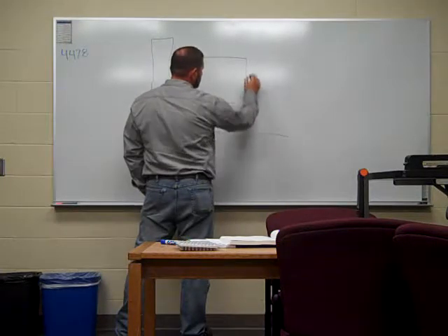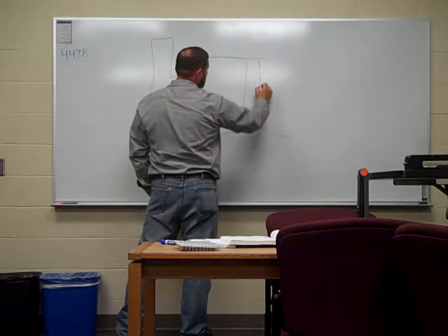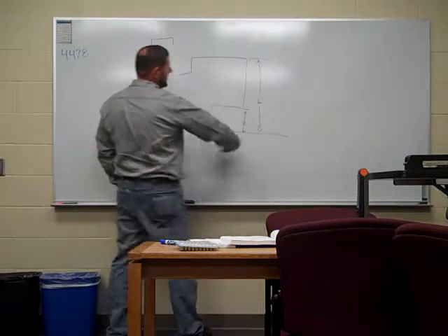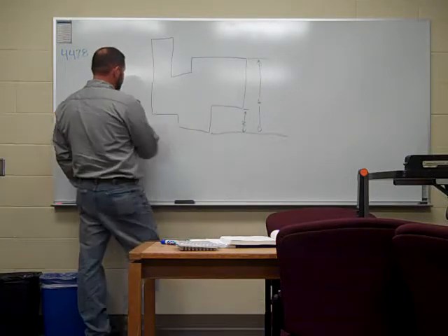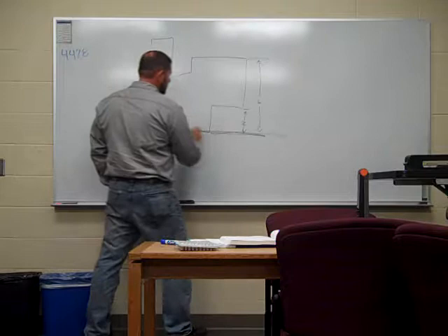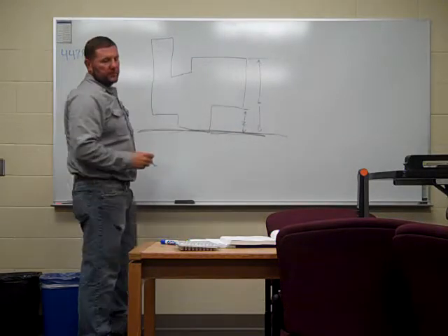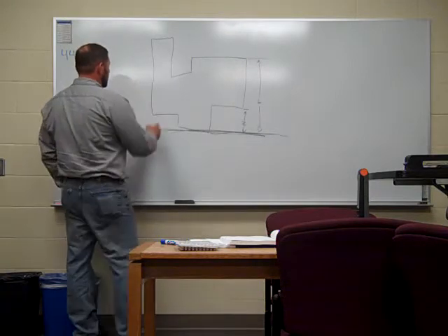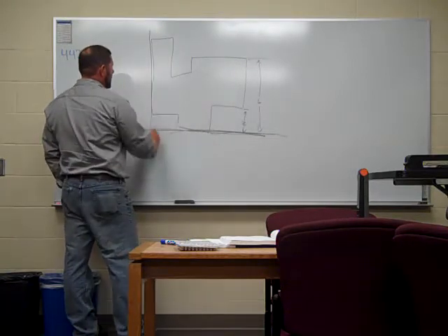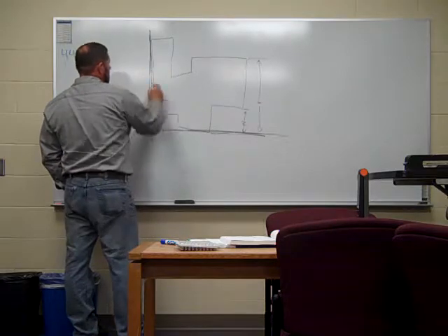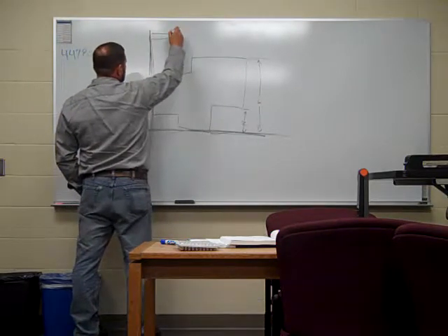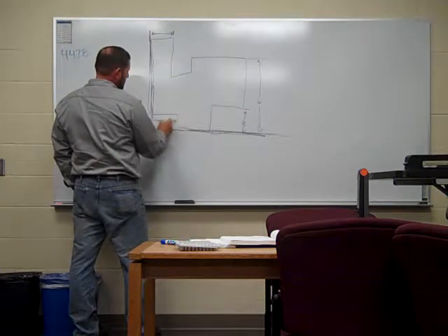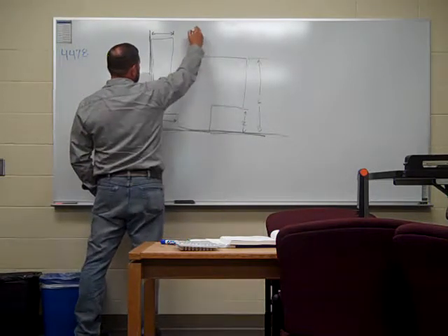let's say that's 2 inches. Let's say that's 6 inches. So they're using that one, this plane right here, to measure all those dimensions. And they're giving you every dimension. Same as here. They might use this right here as their datum, and they're measuring all these dimensions off of here. Same here. Measuring every little dimension off of there.